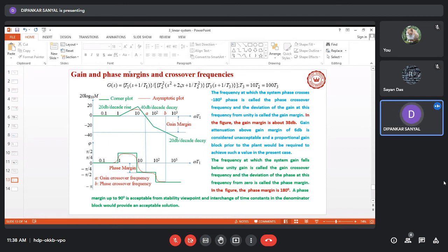If the phase lag is 180 degrees, it implies that when we ask for growth, we get a decay, and when we ask for a decay, we get a growth. So the output is completely corrupt. Because of that, a phase lag of 180 degrees is considered totally unacceptable.